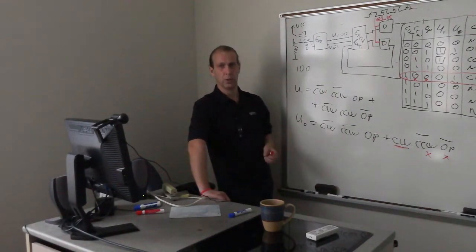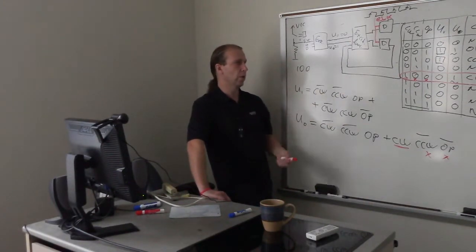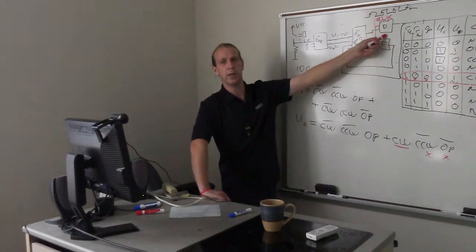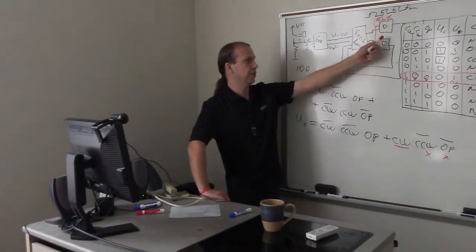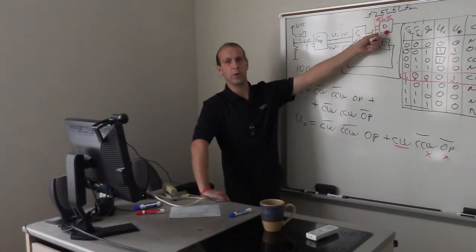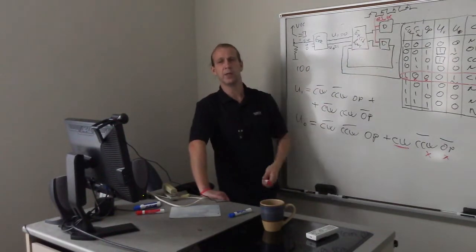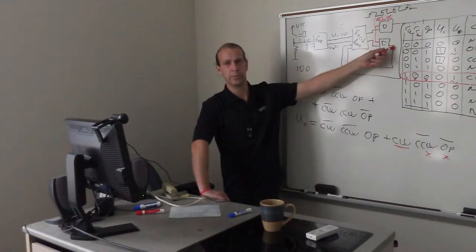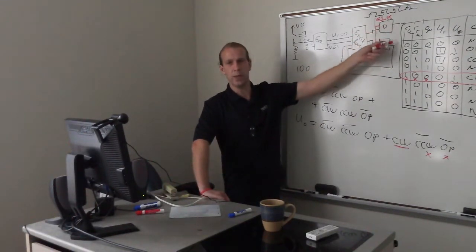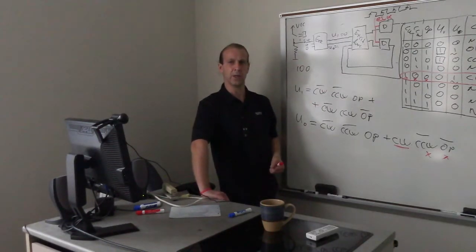So there's no set initiation point? Initiation point is whatever state these 2 triggers will be in when we turn on the power. For example, this trigger, after turning on the power, may be in state 1. This one can wake up in state 0. In this case, the combination will be 1, 0. Right? What is combination 1, 0 with respect to our labels for the finite state machine A, B, C, and D? We don't know. We did not yet discuss it.